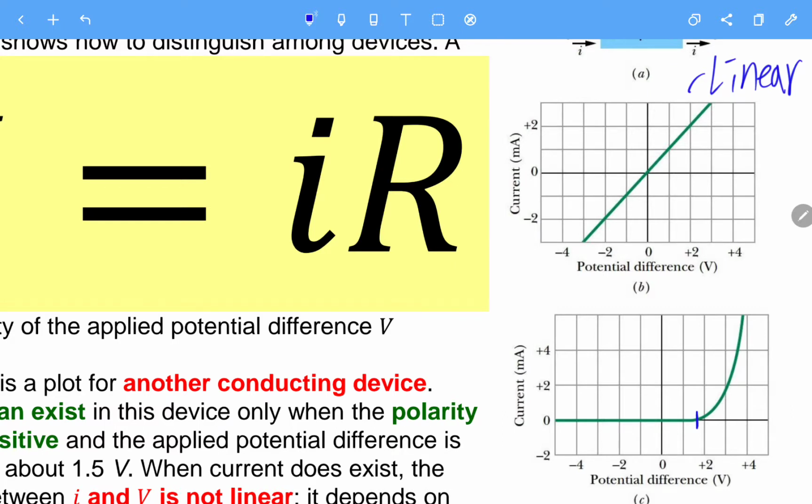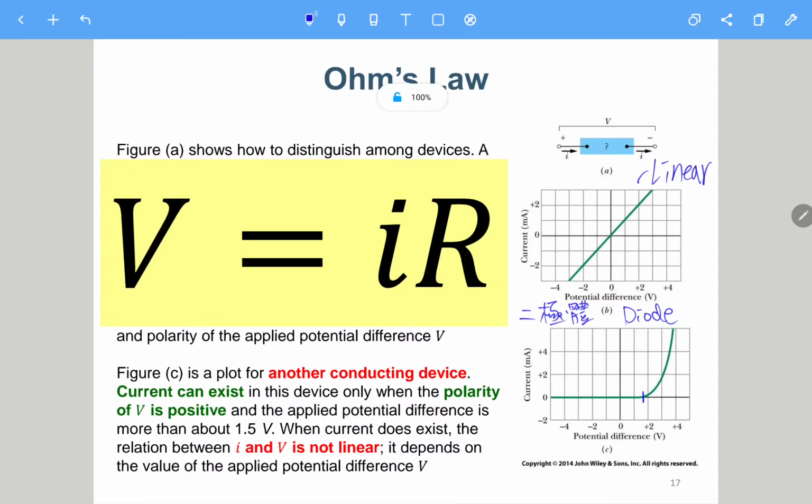Okay, actually this is the so-called diode. In Chinese, it is called 二极体. So the electrical symbol is like this. If you apply a voltage, for example this one is V and this one is 0, and V is a positive value, then there will be no current going through it. It will be somewhat like an open circuit. But if you have a forward voltage, this is 0, then there will be current going through it, and the current will increase exponentially, not linearly.